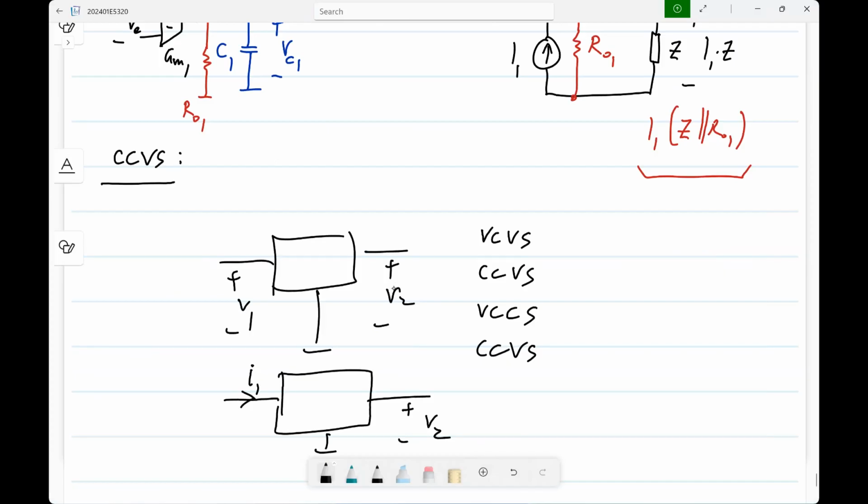Yeah, so which kind of controlled source it is is characterized by the input and output resistance. The idea is, if it is voltage controlled, then it should not be sensitive to the series resistance of the input voltage source. Even if you have an imperfect voltage source, it should sense the voltage without being affected by the resistance, and it will do it only if the input resistance is very high or infinity. Similarly, if it's a current controlled voltage source, it should not be sensitive to the internal resistance of the driving current source. Okay, so that's what distinguishes.